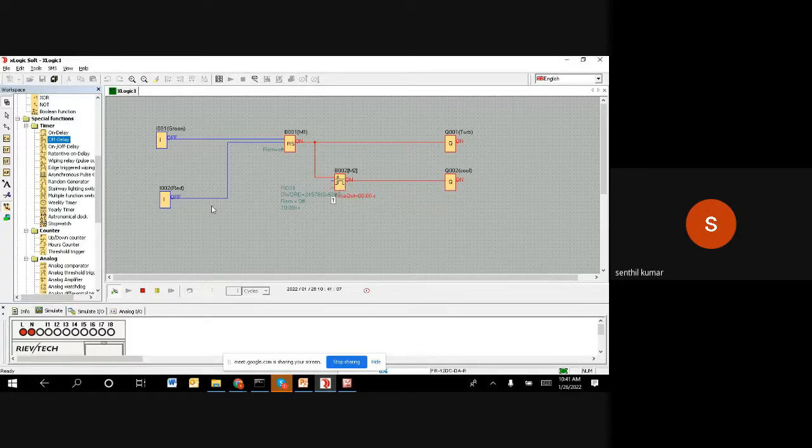So now if I stop it, our requirement is that the turbine has to go off immediately, whereas the cooling pump has to run for the next 10 seconds. Obviously it would be 1 hour, but in our example, 10 seconds later it has to stop. So I'm going to do the off now. I switched off. You can see the turbine went off, but the cooling pump is still on. 6 seconds, 7 seconds, 8 seconds, 9 seconds, 10 seconds, off. So basically it stayed on for 10 seconds, and then it switched off by itself.